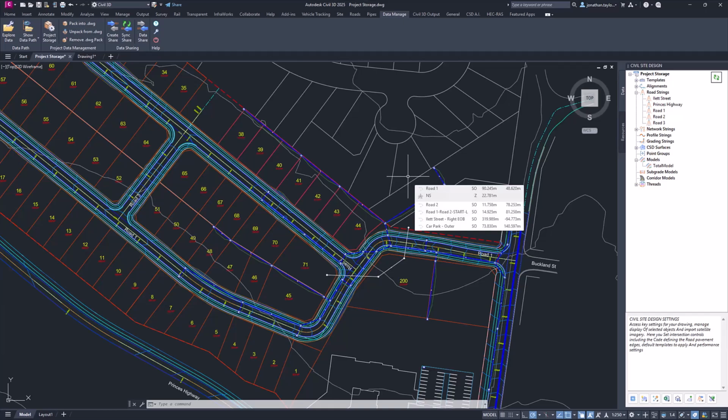Yeah, the other question is about what happens when you crash, which we talked about before, but the software offers you options about restore. Another question was about whether or not someone opens the drawing up in just plain AutoCAD without Civil Site Design installed. The zip file that gets bound inside the drawing doesn't get touched, so as long as nothing breaks it, it shouldn't be a problem. I think those were the main things that were probably pertinent to let everybody know about. Yeah, it's only Civil Site Design which gets access to that data folder inside your DWG. There's no other piece of software that will.